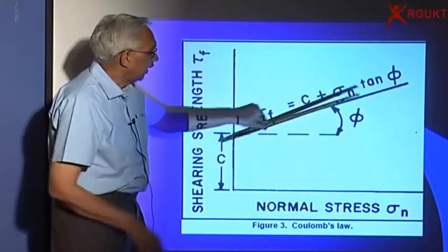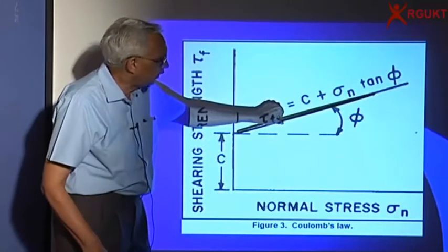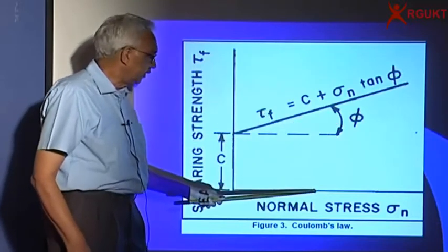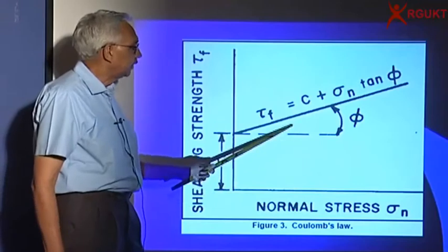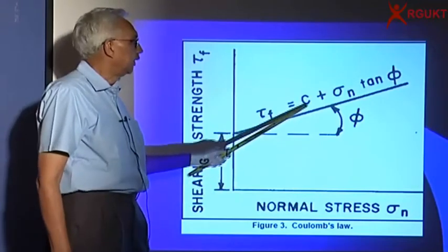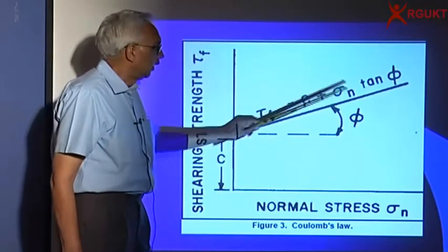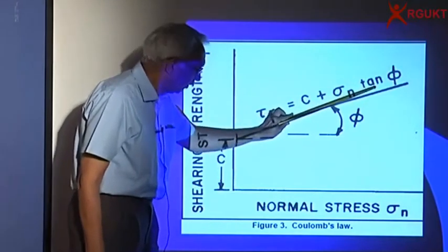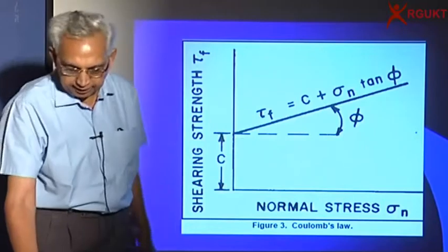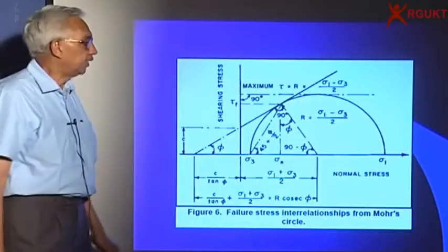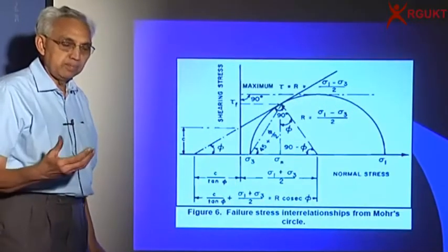Look at the angle made by the failure line, which means as you increase the shearing stresses, it can rise and reach up to this point. There is no state possible beyond it, and that is why we call it an envelope. Please remember, this is what Coulomb originally started, and then what Mohr said was, instead of looking at normal and